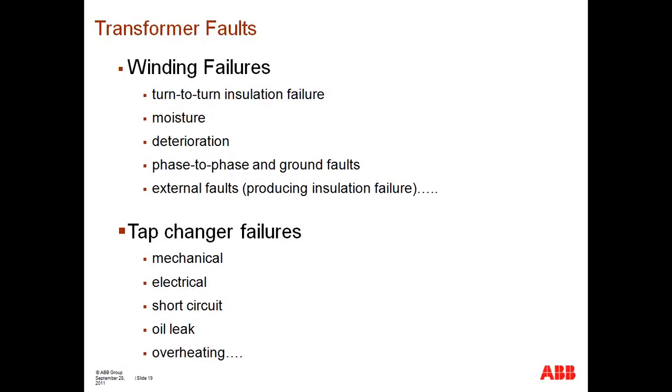So each time these things occur, there's contraction and expansion of the windings, and each time that movement of the winding occurs, there's a bigger chance that the insulation between windings or between turns can start to break down and give in, and in turn provide a path for an electrical short circuit between either winding, core, or turn to turn.